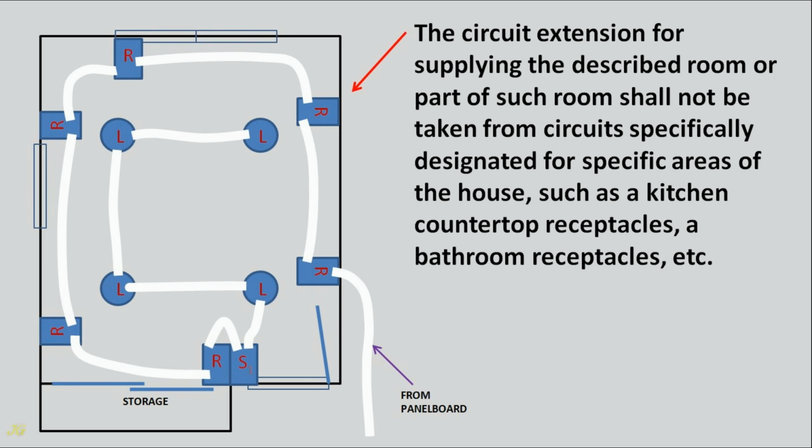The circuit extension for supplying the described room or part of such room shall not be taken from circuits specifically designated for specific areas of the house, such as kitchen countertop receptacles, bathroom receptacles, etc.